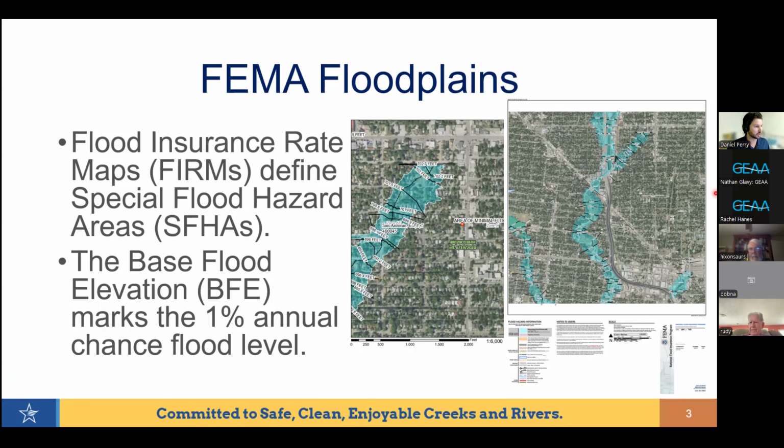rules. So just to give perspective, the FIRM here is on the right, and then you have this flood hazard information legend down in the lower left corner. That gives you perspective on the flood zones. And then the cross sections themselves are these black lines, and the elevations, the 702 and so forth feet, are the elevations of the 100-year storm.